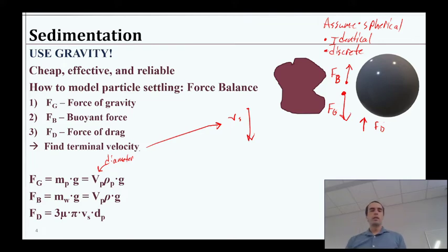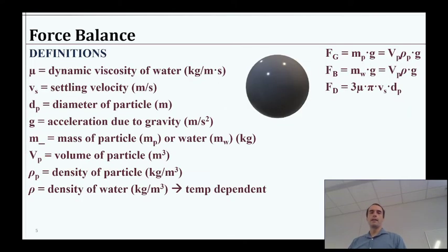One thing to note here is our density of water and our viscosity are both temperature dependent. So sedimentation operations in the middle of winter are a bit different than in the middle of summer. Water's a little more viscous when it's colder, and slightly less dense when it's hotter, for example.